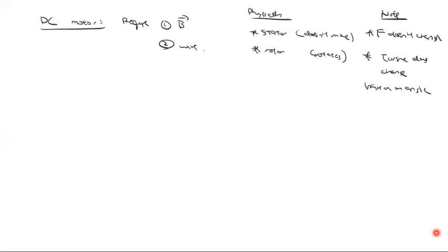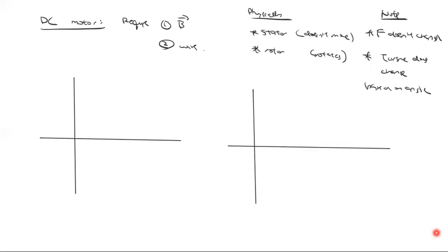And that's why typically you'll get questions about, okay, as the motor turns, what is the sort of graph of, say, force and torque? And so your force, if you're graphing force against time, because you understand F equals BIL sine theta, but theta equals 90 degrees, then it's going to be BIL.